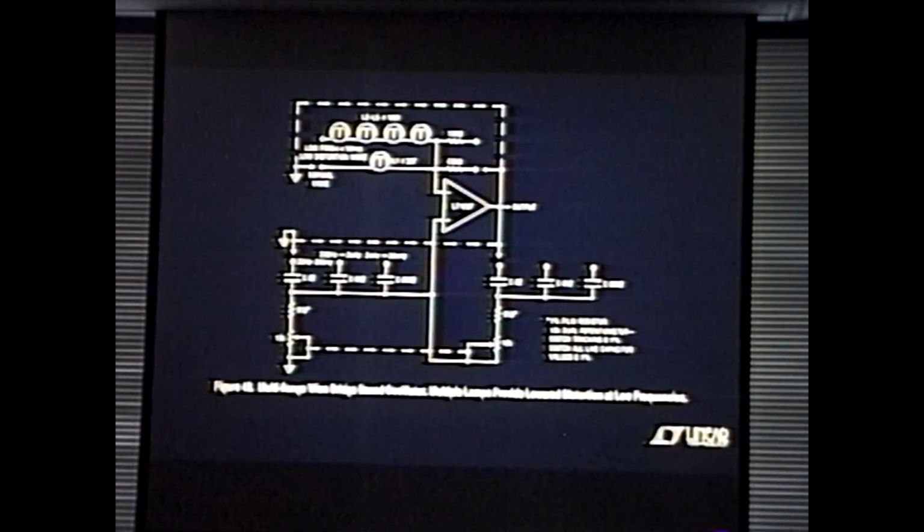So what you do on the lowest range, say down 20 hertz to 200 hertz range, and on the bottom here, you fatten up the thermal time constant. And the easiest way to do that is to add more and bigger lamps. You'll notice there's not only 4 lamps, I've gone to a different number here. That lamp's physically larger. Okay, so I just want a lot of thermal time constant here to be able to average the relatively low frequency here.